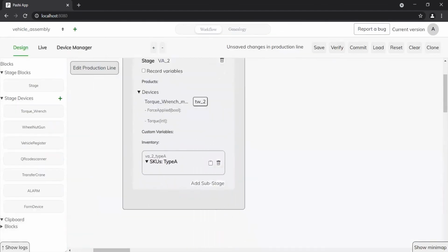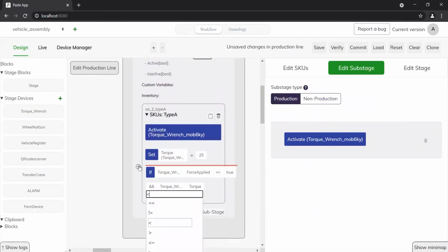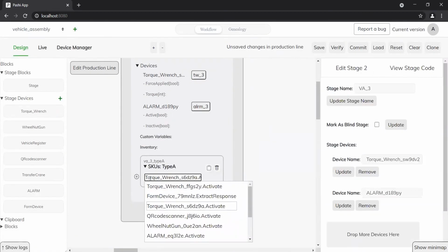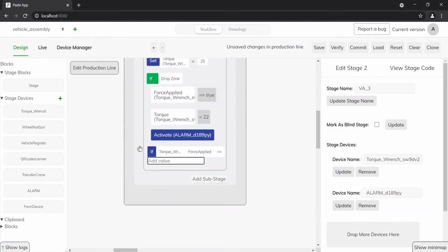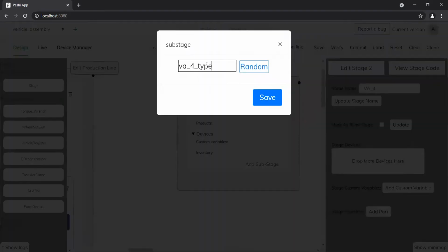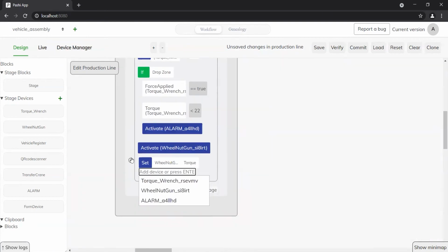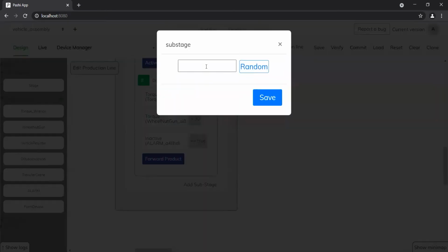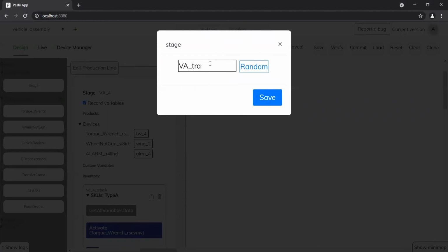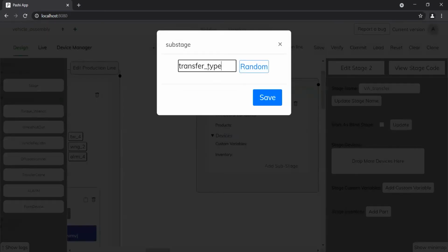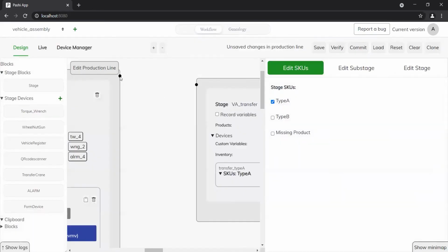In the next few stages, the operators attach the silencer, fuel tank, front exterior panels, and the front wheel to the vehicle frame. The tightening operations for these stages are similar to the first stage, and we will enable Poke-OK logic for each operation. Once those components are securely fixed to the vehicle frame, the entire assembly is transported to a parallel conveyor belt